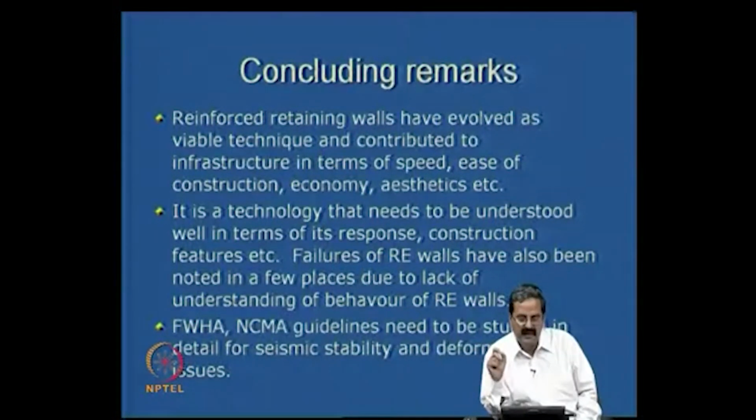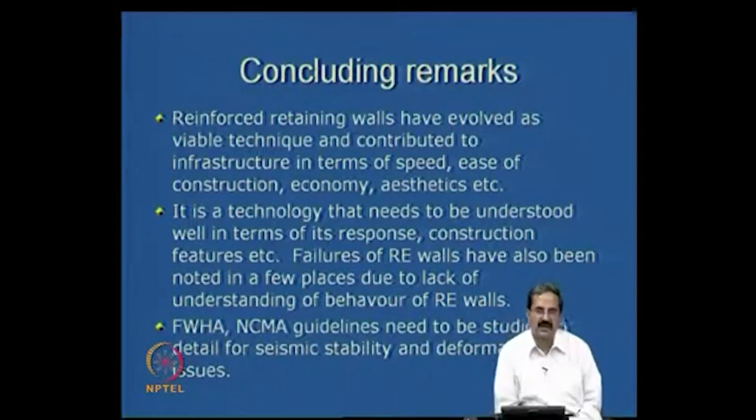Very importantly, one should understand that this technology needs to be understood in terms of its response and construction features. The RE wall is actually a construction technology. The way it is constructed in the field is very important, and I have seen many cases where the specifications are all right, but it is not done well in construction: the way you join, the way you erect, the way you place, and the time of placement also.